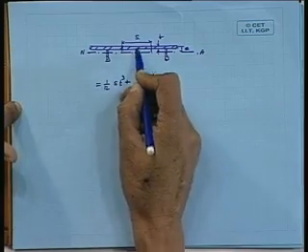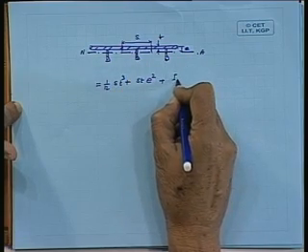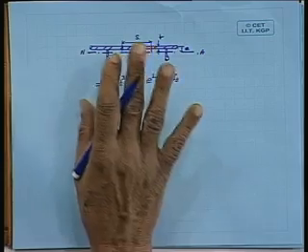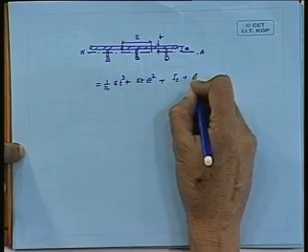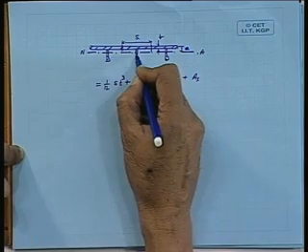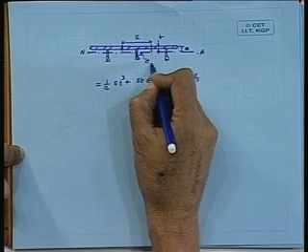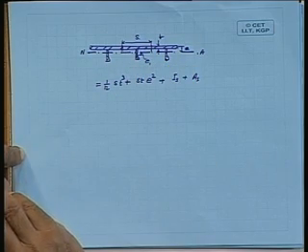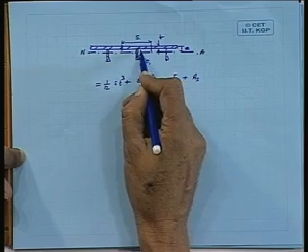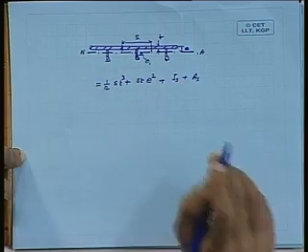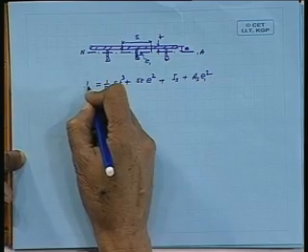To that I add the I of the stiffener, whatever you get for this rolled section from the table about its own neutral axis, plus area times, and then again this one will be known to me, because I know the centroid location with respect to this end, and therefore I can find out how much is this distance. So this will become